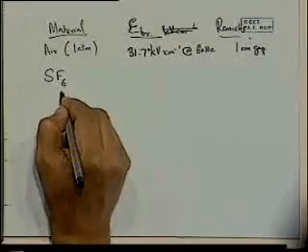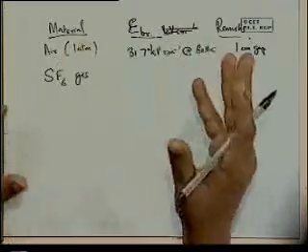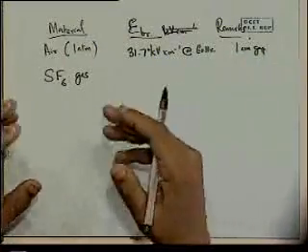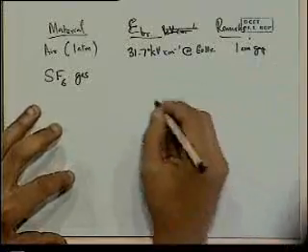Sometimes you want to test the material to higher and higher voltages, because the material itself has not broken down, it's the air between the electrodes or the probes that has broken down already. So what they do sometimes is to use this gas, SF6. You fill the chamber with SF6 and then you do your measurements, because SF6 can sustain higher voltages before it will break down compared with air.